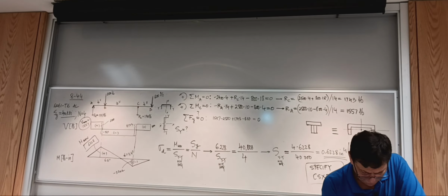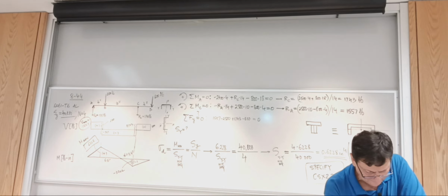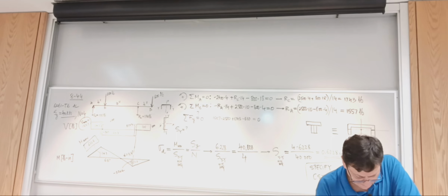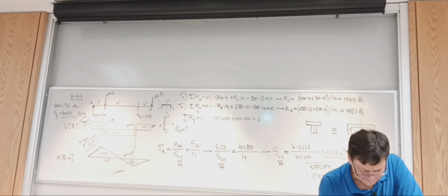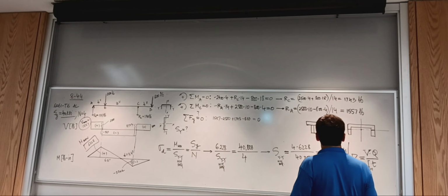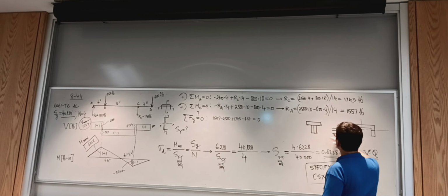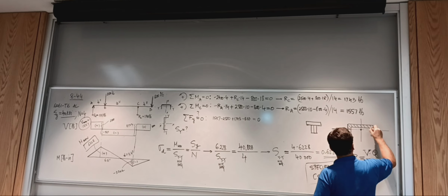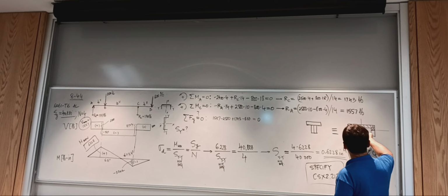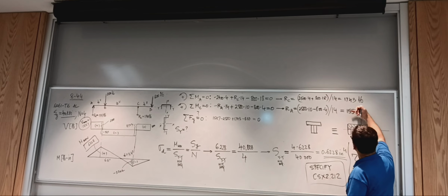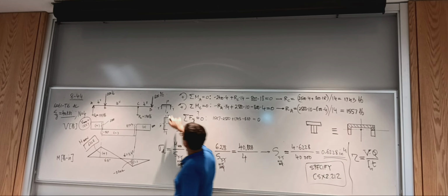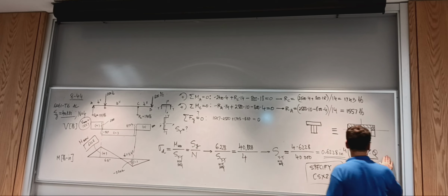Okay, so I'm on page 474, and there are some graphs here. It shows the neutral axis is the maximum shear stress. Now we can leave it as is. We can treat it as a T section. But the expectation is the same, that the first moment of area is to be evaluated for what is above or below the centroidal axis, which would be the y-axis here. So yeah, we need to use the general formula.